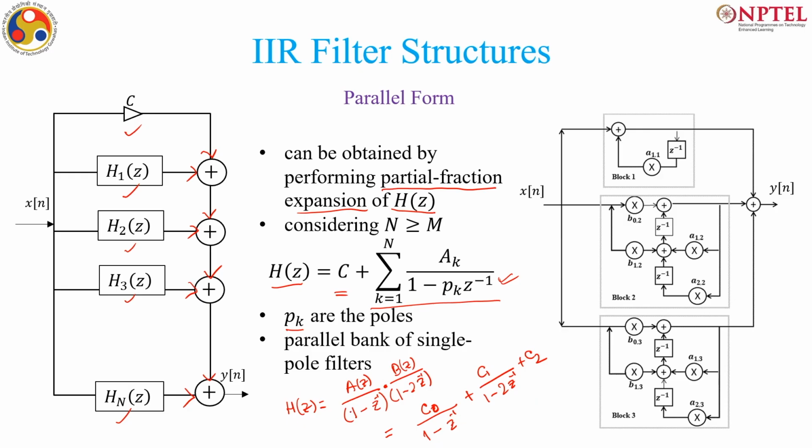And now, there are methods to obtain these values c0, c1, c2, and again these may not be just constants, they may be c z inverse plus some d, something like that. So, how can you get them? There are rules to solve these equations to obtain the coefficients of the partial fraction expansion. Typically, in this cascade form, what are these coefficients or values giving? These are basically giving you the poles, because say in this case the pole is at 1, the pole is at z equals 2, and how do you know? Because at the pole this term becomes 0.